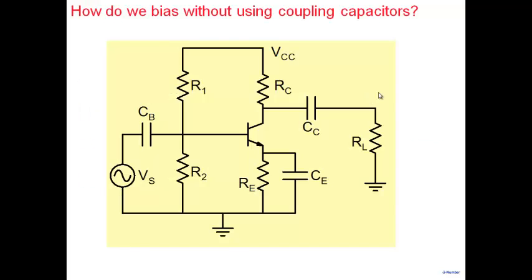We have seen this particular circuit of a common emitter amplifier with a resistive biasing here. And we have seen that in this particular circuit, what you require is a capacitor from this end to couple in the signal. You require a bypass capacitor here, and you require a capacitor to couple the output signal to the load here. And these capacitors are typically, if you want lower cutoff frequency in the range of, let's say, a kilohertz or hundreds of hertz, these capacitors typically come out in microfarads here.